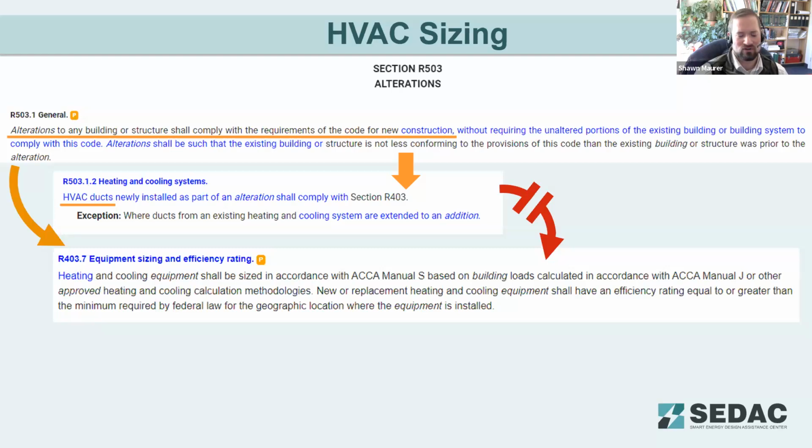And again, this is for existing buildings, ensuring that as we're upgrading systems, we're not just doing a one-for-one replacement of a system that wasn't working properly and is vastly oversized. It's going to be inefficient, even if we're putting new equipment on it. We want to ensure that the equipment is properly sized, both saving energy, extending the operating life of the equipment, and saving on capital costs from not putting in equipment that's too large for the loads in the building.